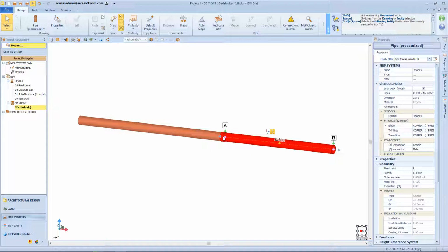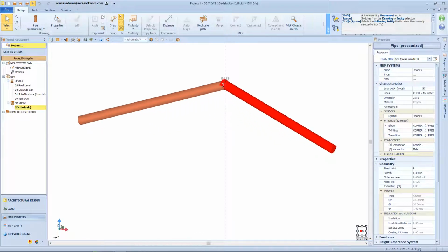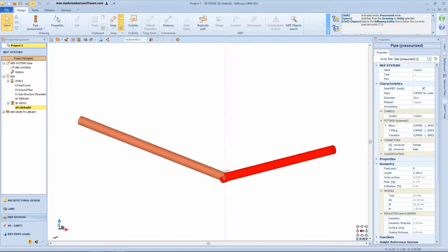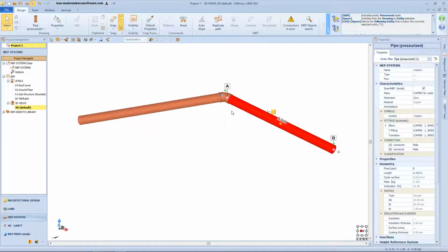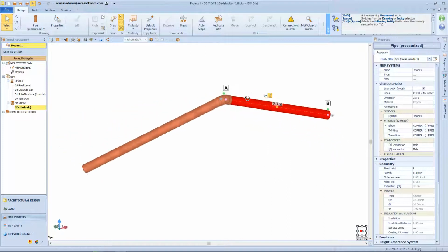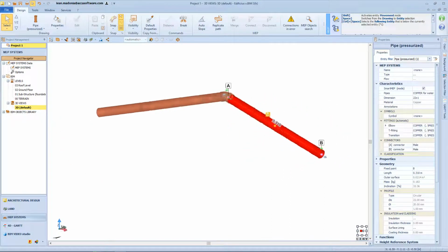After moving the connection in correspondence with the bending point sought, proceed to the creation of the curve in the vertical plane by clicking on the green arrow that appears in correspondence with the joint, thus reshaping the broken pipe in the vertical plane, starting from the definition, graphically or by typing the keyboard value, of the height that the curve must have. In this way, a pipe can be quickly remodeled by automatically creating curves based on the dimensions set with the green arrow.